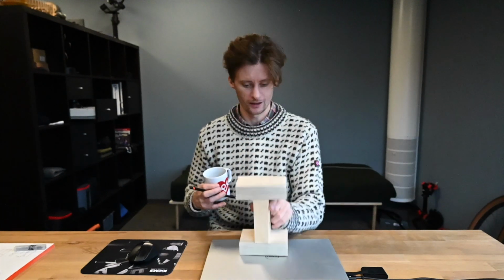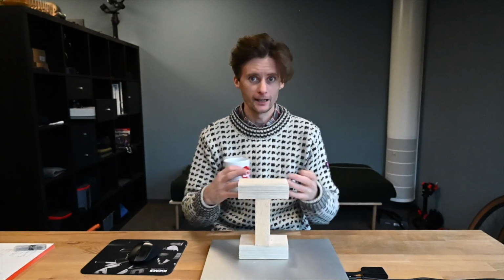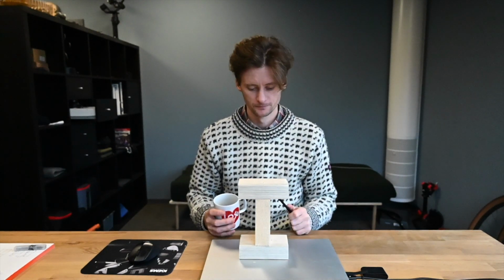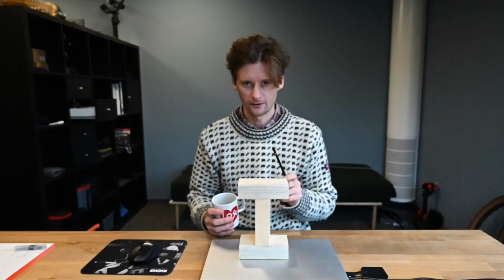Why is this important? Well, because we want as little movement as possible in the machine. So this is not a great tool for cutting a flat piece of material, but it is a great tool for cutting this type of 3D object. Let me show you what that tool center point looks like on our tilter.